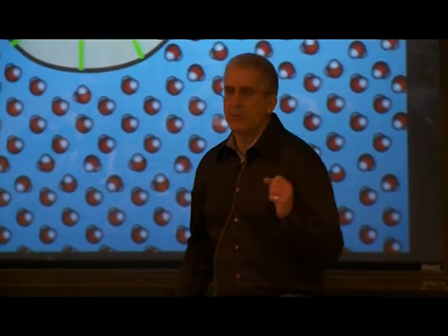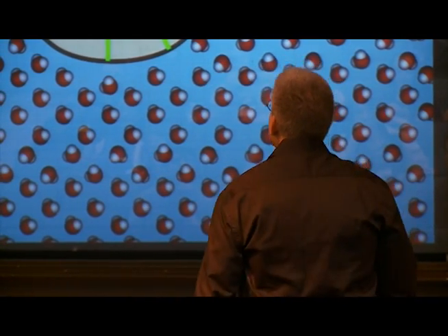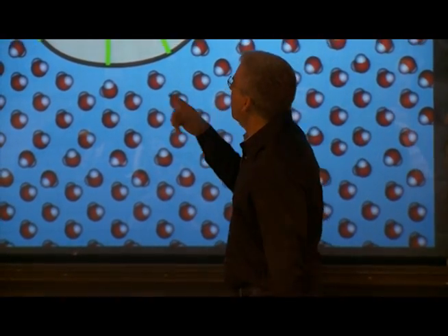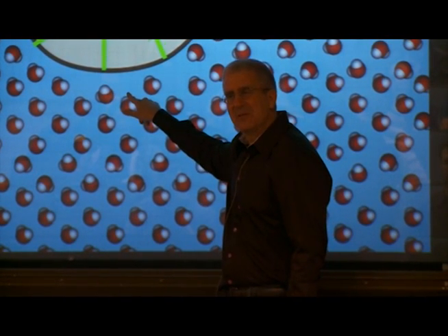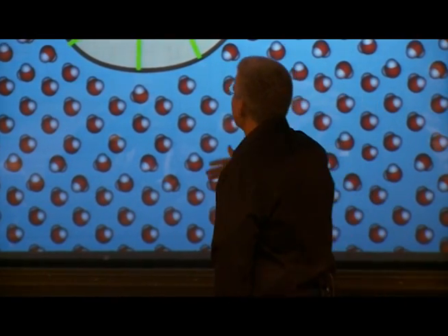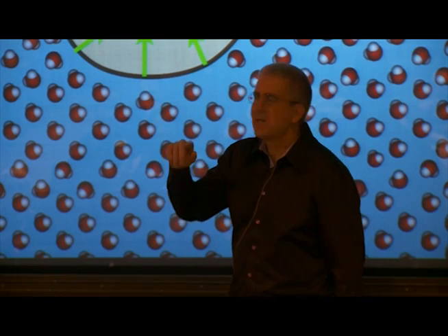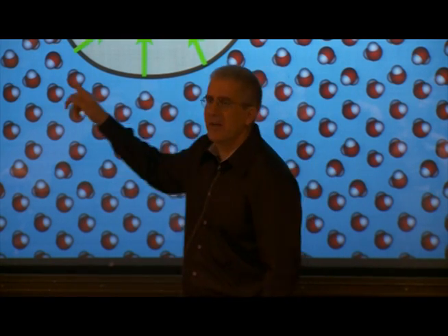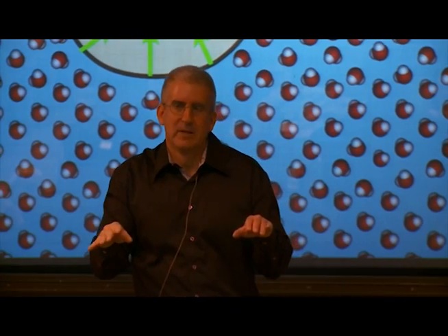Okay, now, what does that have to do with normal forces? Well, the idea is the following. If I look at individual molecules, their ideal state is to be surrounded by as many other molecules attracting them, so they really want to be buried in the center of the fluid. But they can't all do this, and the ones on the outside are the ones that are the most unhappy because they have fewer neighbors. They feel less popular. So how can they become more popular? Well, the answer is they burrow into the fluid. And the way to put the least number of molecules on the outside is to flatten the surface. So the net effect of these intermolecular forces is that you want to flatten the surface.